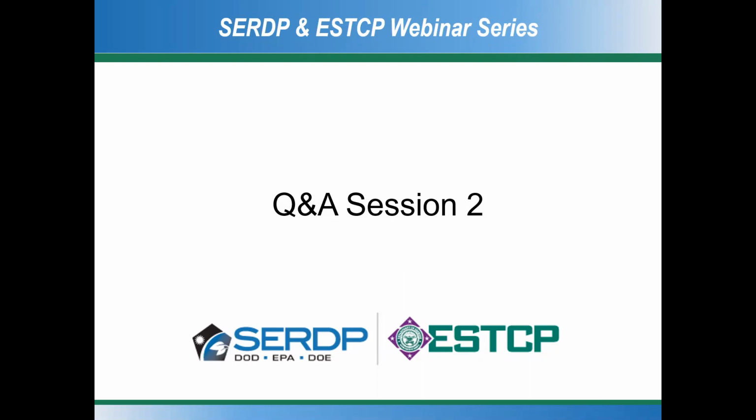That's research that's just emerging out of my collaborator's lab at UCLA, where sorption to GAC, or granular activated carbon, initially didn't seem like a good idea. 1,4-dioxane doesn't sorb very well to activated carbon, and it desorbs very easily once concentrations go down. So if you bio-augment GAC, for instance, with CB1190 and you have active degradation, then you can make sure the 1,4-dioxane becomes degraded. You increase the adsorption capacity and you decrease the risk for desorption. So I do believe there are a lot of other potential combinations that should be considered.